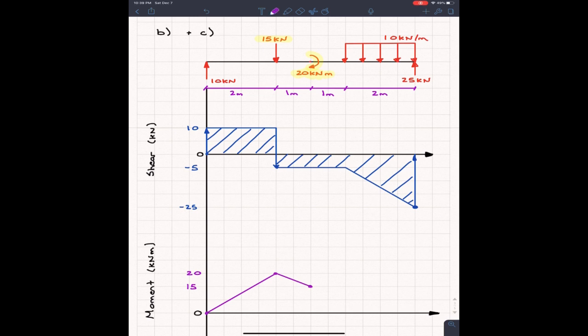And the reason why professors love them is that they have the same effect as concentrated loads. As you guys remember, when we have a concentrated load, we jump our diagram. When we have the 10 kilonewtons going upwards, our shear force just jumped up by 10 kilonewtons. When we had 15 kilonewtons going downwards, our shear force would drop by 15 kilonewtons. And that kind of makes sense in our head. That one's not too bad.